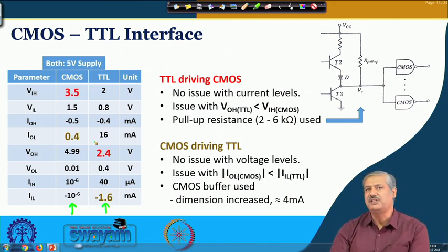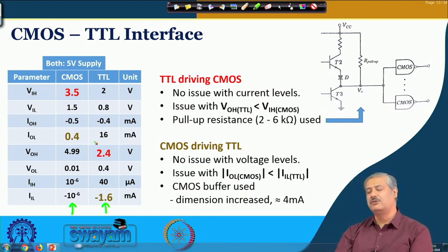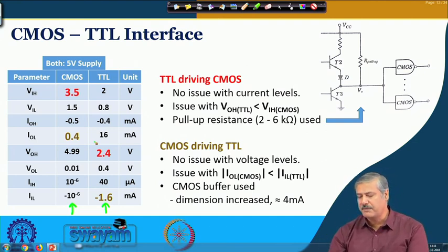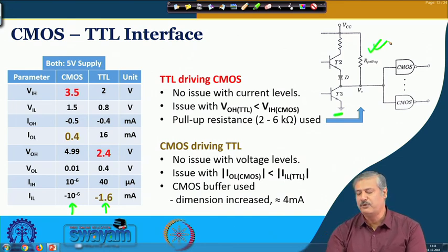So that is the only problem, otherwise there is no issue in connecting a CMOS load to TTL. And for that, how is it overcome? It is overcome by having, this is the TTL stage, this is the output stage, a separate external pull up resistance that you see over here, which increases this voltage level more than what you can get in normal TTL cases.